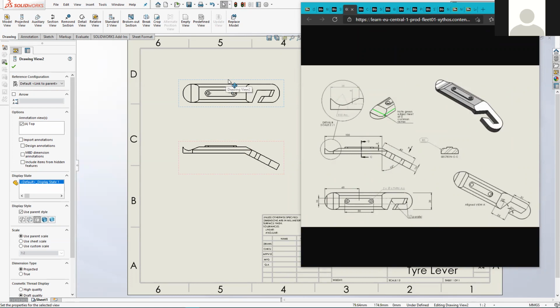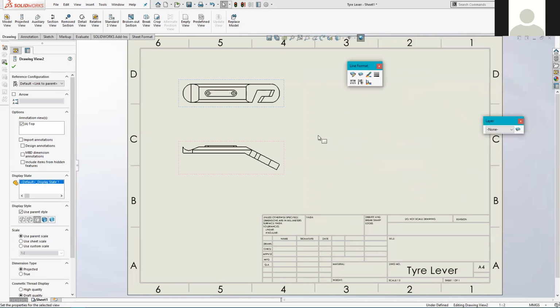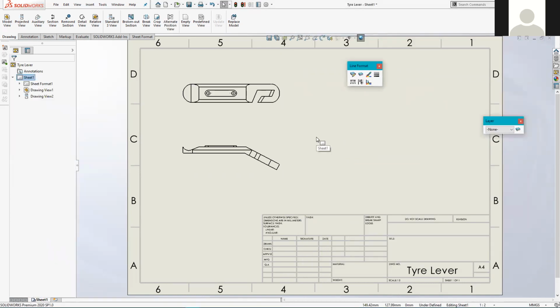So we're going to project upwards and get the same view, whereas this one's been projected downwards and you've got the same view. So ours is slightly reversed. And if you need to change that, because I'm aware that often SolidWorks comes set up for the US market, and the US market would use first angle primarily.